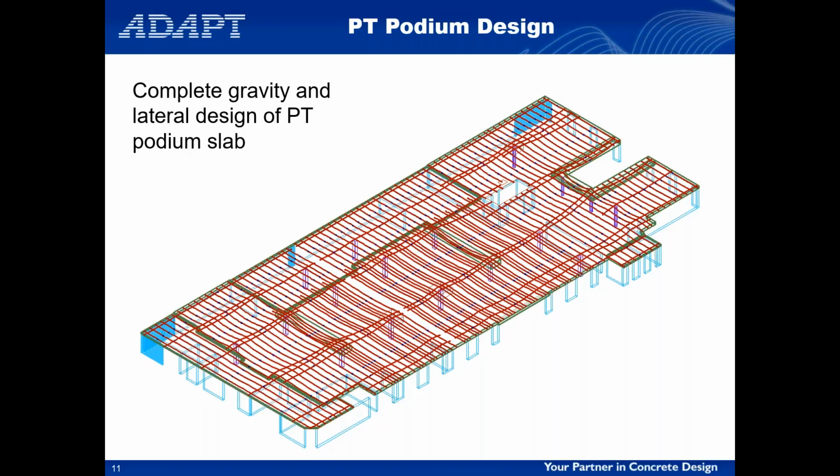So that's just one piece of advice to think about, and you can actually just do a quick comparison, take one of your models, run the two and see what happens. The big difference will be that some of your post-tensioning from the podium will go into your foundation as opposed to being available as pre-compression in your slab. So the PT design is pretty straightforward.